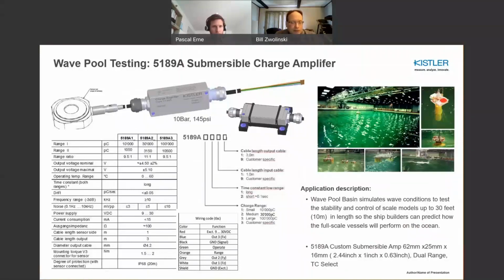The model itself is a very small watertight compartment where you can't put electronics other than the data acquisition system. So you need IP68 amplifiers, which can be totally submersed with the sensor. In that way, it puts a real good compromise in place, where the signal conditioning and the sensor themselves are fully submersible, and the data acquisition is in the watertight compartment of the model itself.